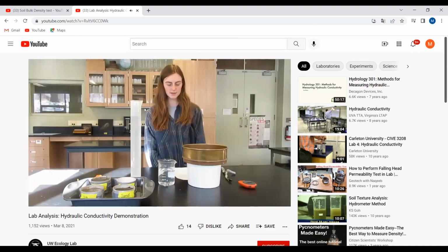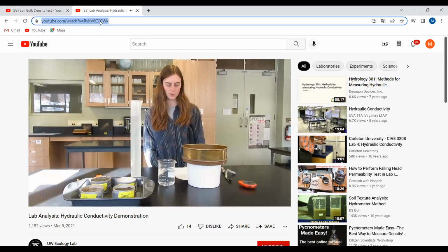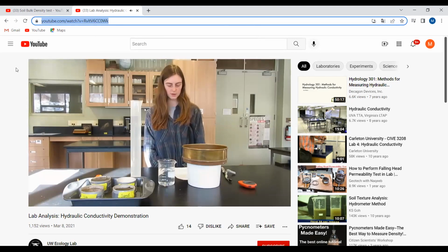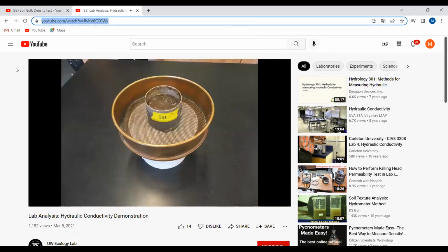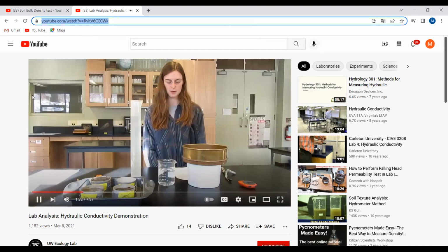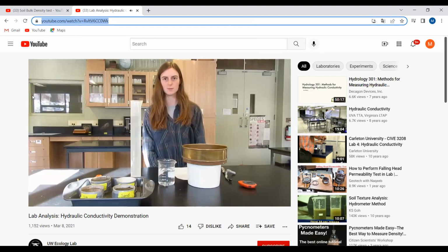The principle of the constant head method relies on getting a constant laminar flow of water through the soil sample, from high elevation to low elevation. The sample must be well packed and saturated with water before the experiment begins. The samples have been sitting in water to become saturated, and note that there's a space between the material and the top of the ring. For our experiment, we will be adding water to the Darcy permeameters until 500 milliliters has been used, or until 15 minutes has run out.